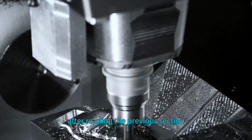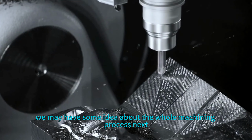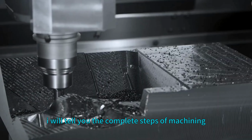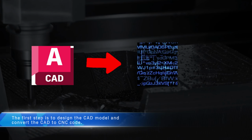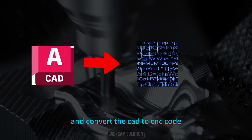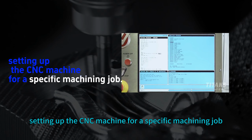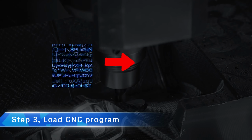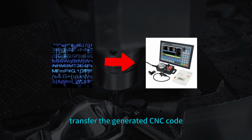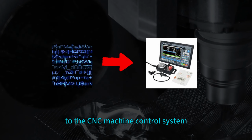After reading the previous section, we may have some idea about the whole machining process. Next I will tell you the complete steps of machining. The first step is to design the CAD model and convert the CAD to CNC code. Step 2, machine setup, setting up the CNC machine for a specific machining job. Step 3, load CNC program, transfer the generated CNC code to the CNC machine control system.